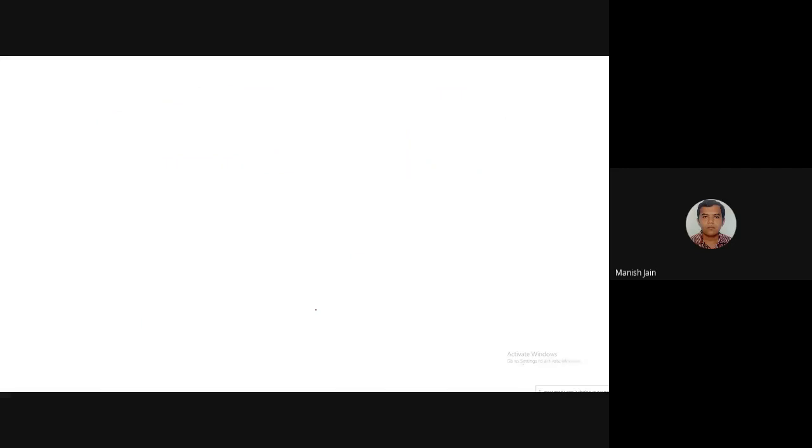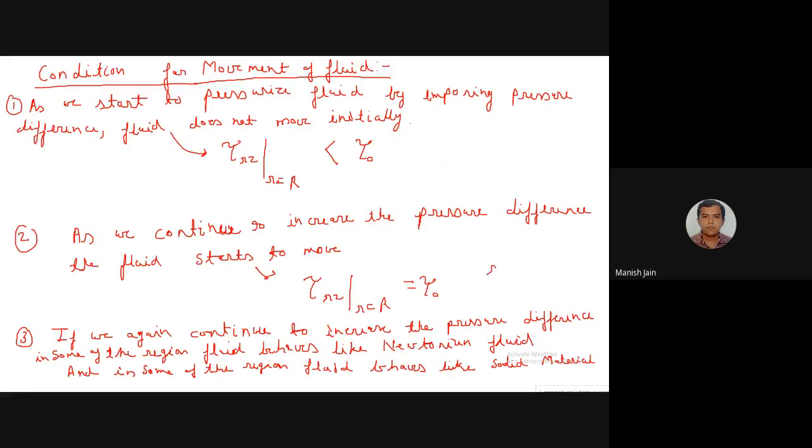Okay, and in this case you can say tau rz at r equal to r naught should be equal to tau naught, where r naught should be less than capital R. So the radius r naught should be less than capital R. Here r naught is equal to capital R, and in this case r naught is greater than capital R, so you will have only the solid part. The fluid cannot move. Okay, now we will solve the problem.